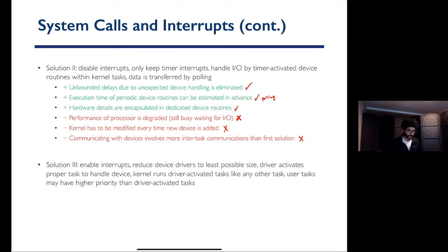So we're going to keep the interrupts enabled. We're going to reduce the interrupt handling to the least possible size. We're going to shrink the responsibility of our interrupt handlers. So they're going to be activated whenever an interrupt happens, and they're going to create new tasks for us every time they handle an interrupt.